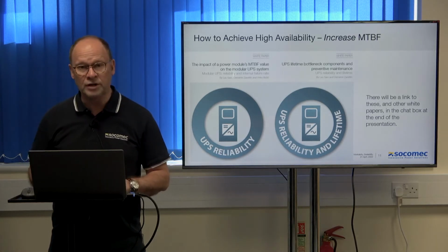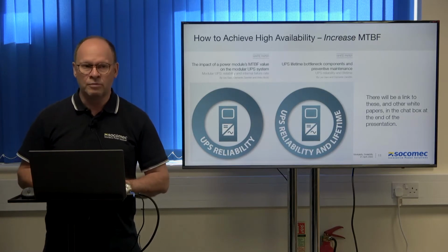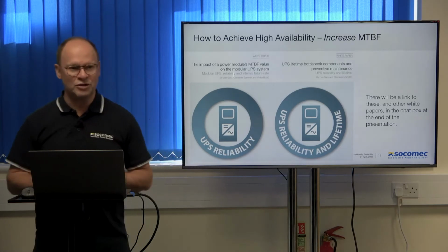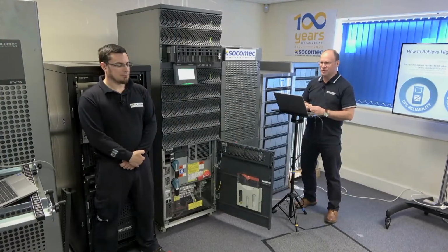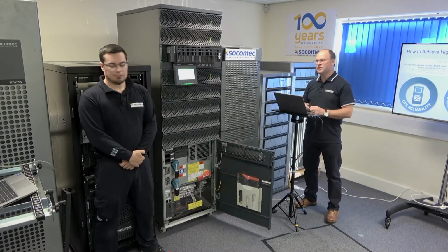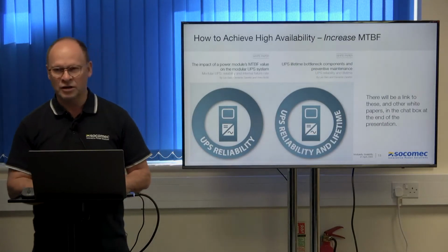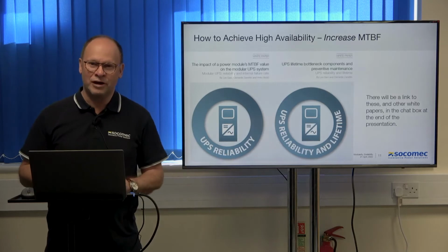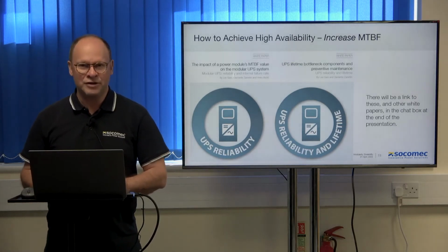And the second point is that the MTBF of our power modules is just over 1 million hours. It sounds like a suspiciously round number, but in practice that's what our design engineers worked out at the design stage. They then had that verified by a university, but for the cynics among you, and I'd include myself as a cynic, the much more important thing is that in the 5 years we've been selling this, the field-proven MTBF is over 1 million hours.